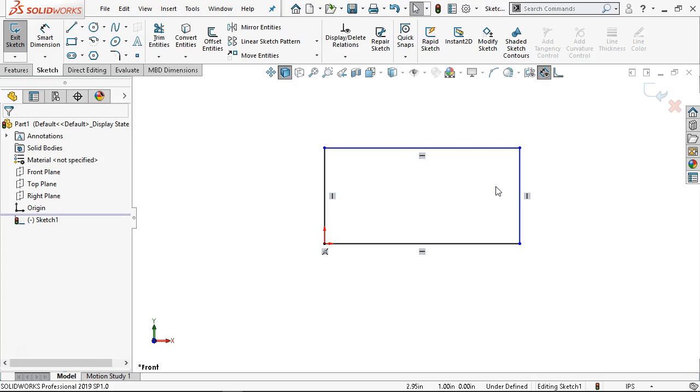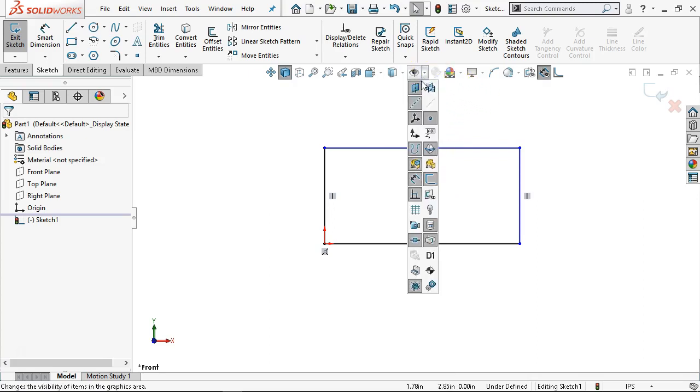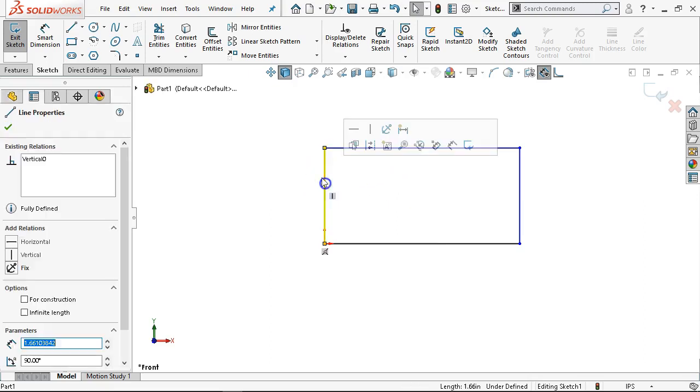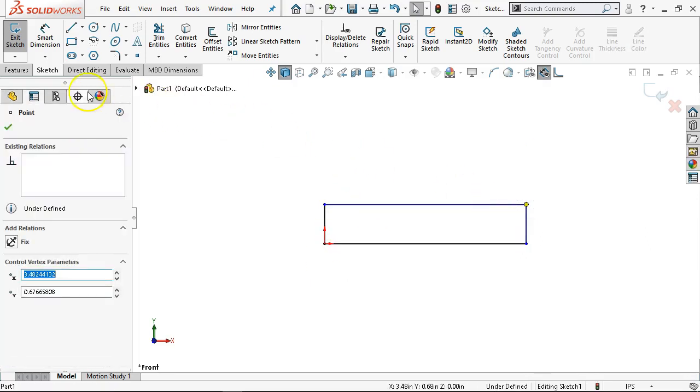I'm used to all of those little green boxes that get annoying, but for 2019, not that bad. But at some point, these little boxes will start to take over. You will accumulate so many relations that I can almost guarantee it will get annoying. And at that point, we'll go back up. I think they're on by default, so if you want to turn them off, that little arrow next to the eyeball will come down to View Sketch Relations, about halfway down on the left. Click on it, and then only what we're selecting is going to show the relations, that it's coincident and that it's vertical.